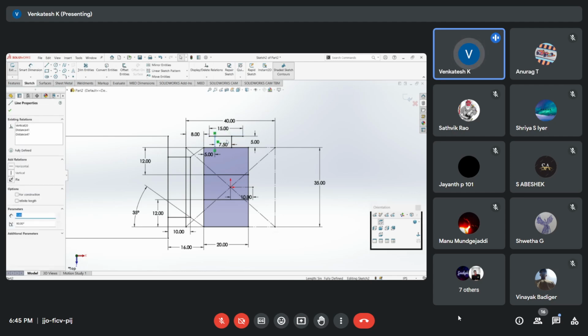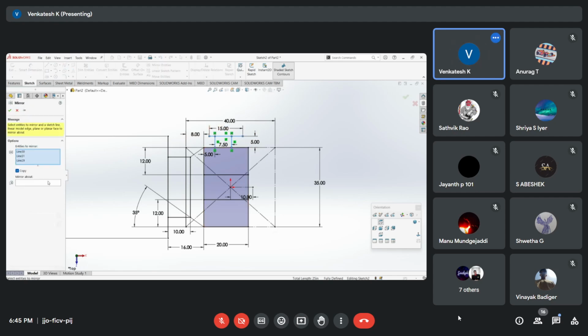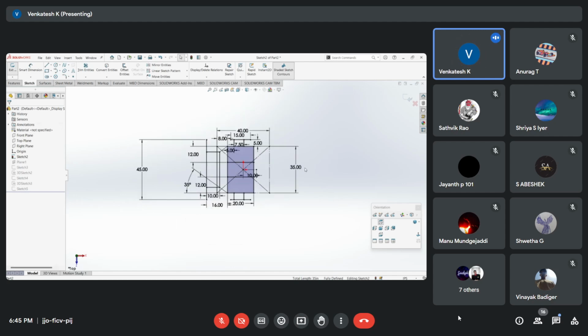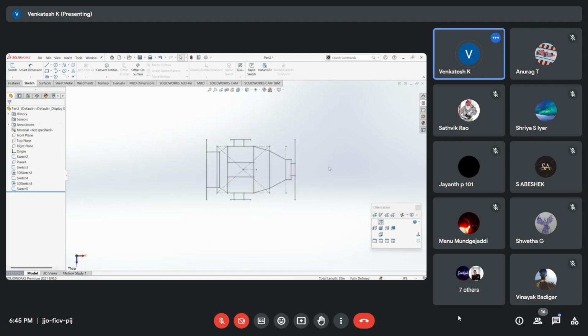In the sketch, you select these using control. In SolidWorks you always select using control. Then mirror them about the reference line. Right. Now you get it on the other side of the chassis also. This will be our side bumper part. This will be our basic chassis.